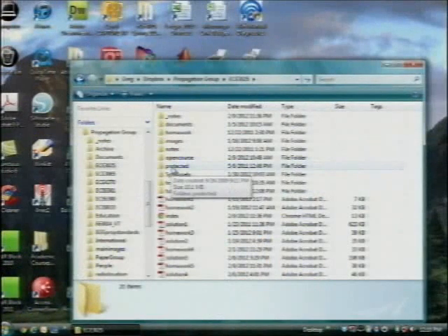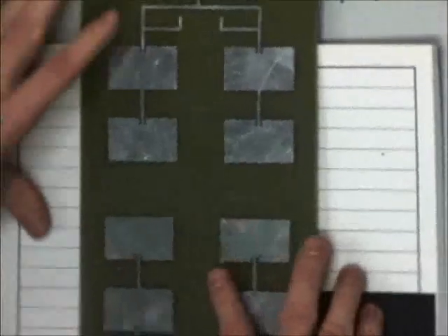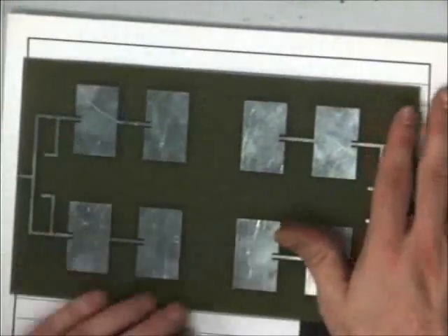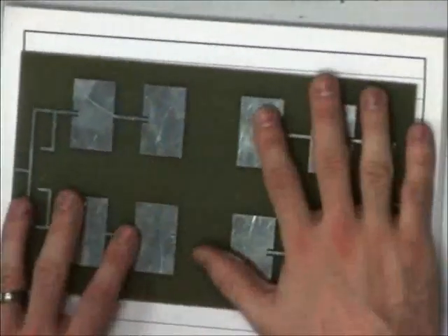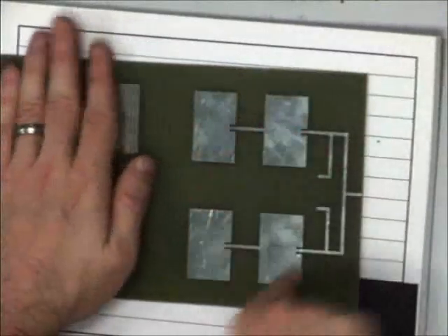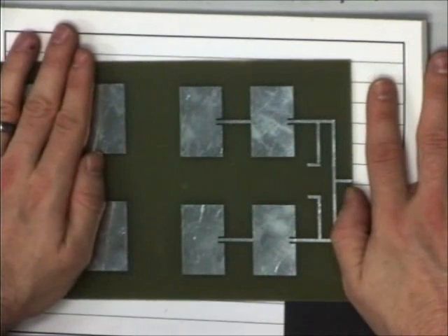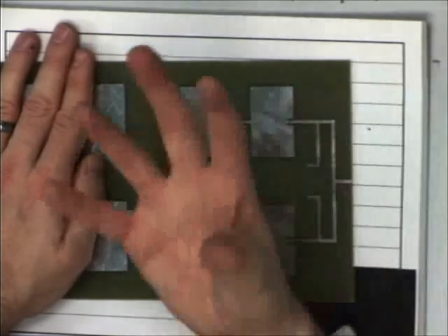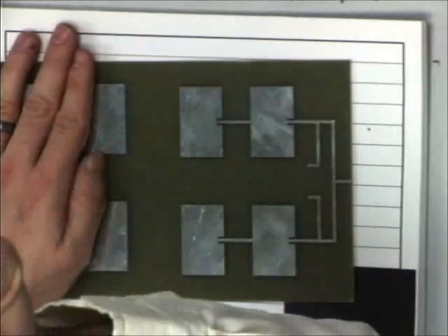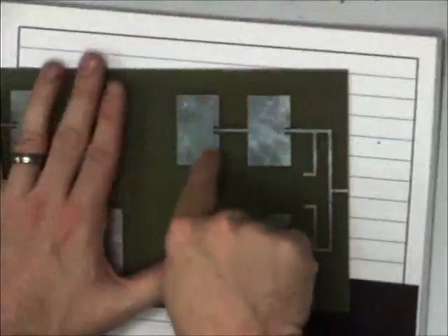Okay, so what is this thing here? This is actually two identical devices on the same printed circuit board. In theory, you could just saw this thing in half and you'd have two of these. Does anybody know what this is? Strange alien technology. Yes, it's an antenna. What kind of antenna? Patch antenna. A patch array. It's actually four patches tied together so that you get a different pattern. You get a really skinny pattern coming right off the top instead of a fat pattern, which is what a single patch would be. And it's interesting, patches are just hunks of metal. This is a printed circuit board.